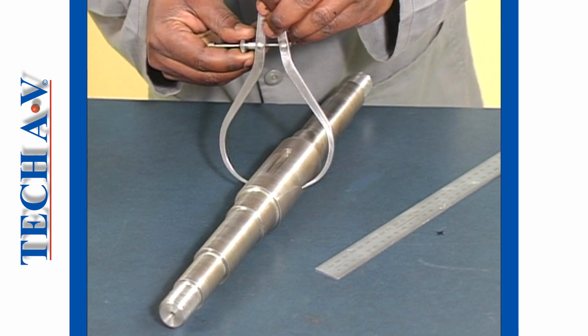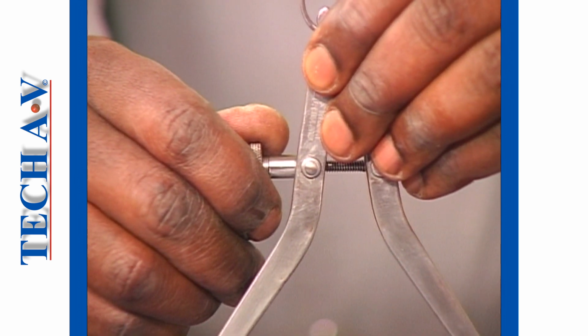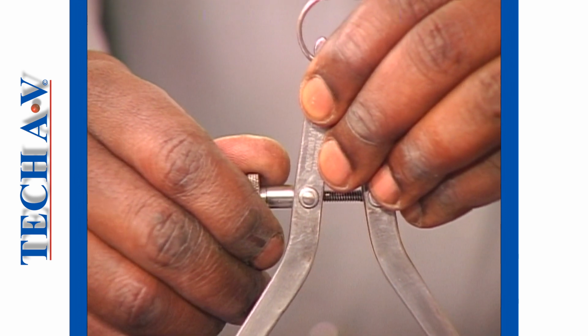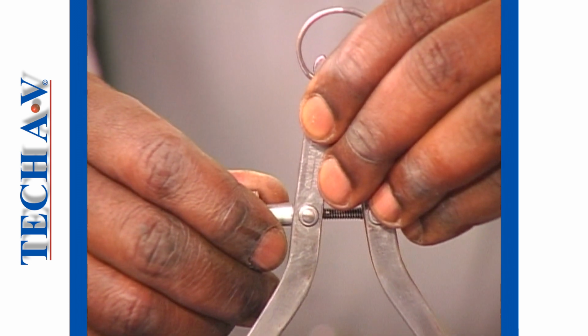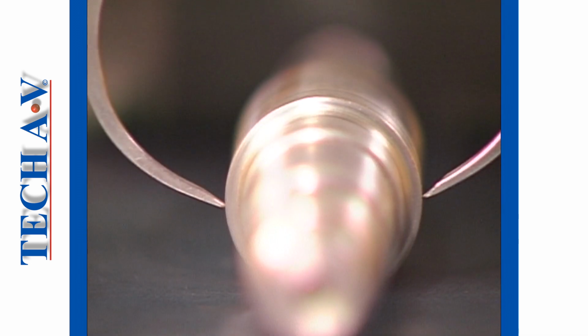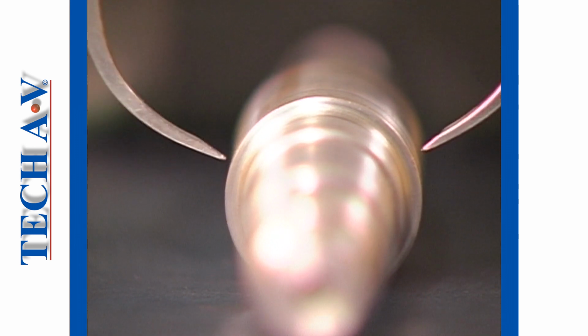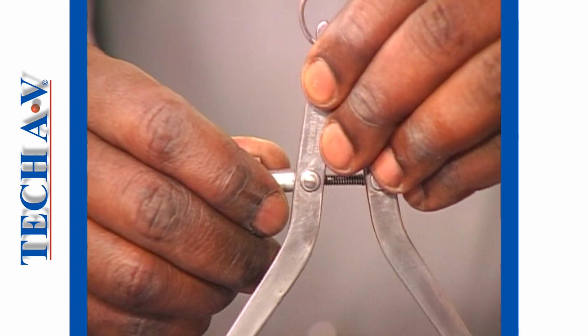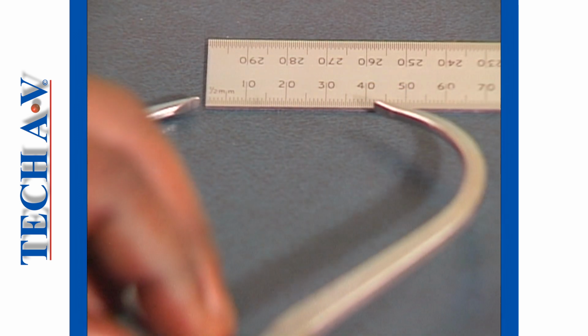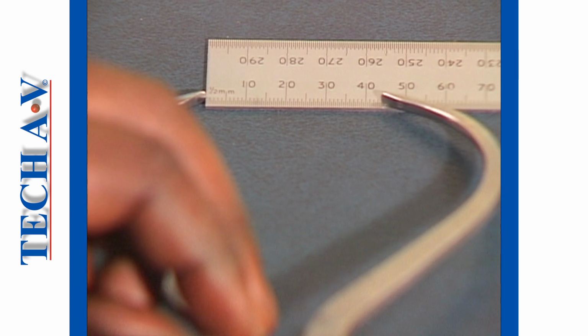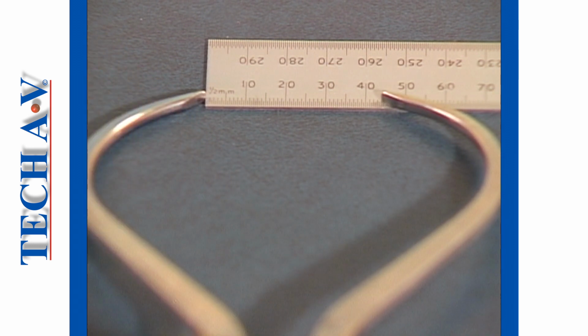Outside calipers are also very useful if you want to measure a diameter, which is not possible to do directly with your rule. The caliper must be adjusted whilst you lift and lower the tips over the surfaces of the workpiece. When you feel the tips just scraping as they move over the shaft, then stop adjusting and take the caliper off. Now, as we did earlier, transfer the caliper to your steel rule, and then read the shaft diameter at the tip of the caliper leg.